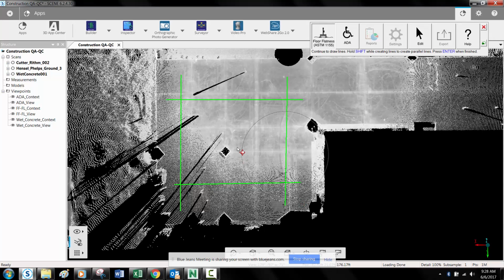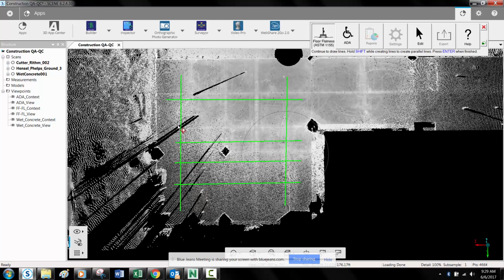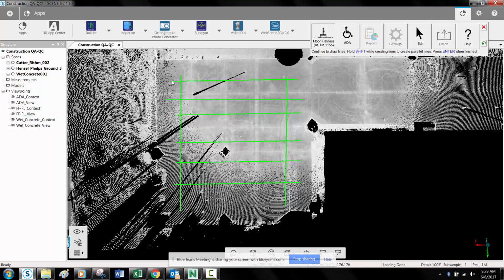And now that we've got our lines written out, actually, again, here's another tip. If you read the instructions underneath the window, by holding the Shift key, it'll recreate a parallel line of the last one that you created. So since this bottom one was my last, if I just hold Shift and make sure to avoid this pillar and what seems to be this little bit here, I can just start creating lots of really quick parallel lines by holding Shift and clicking.